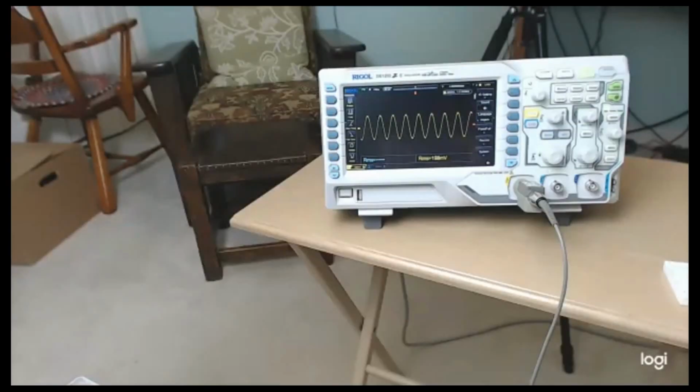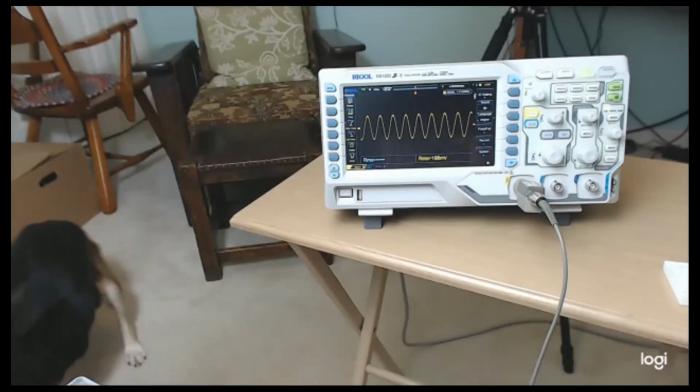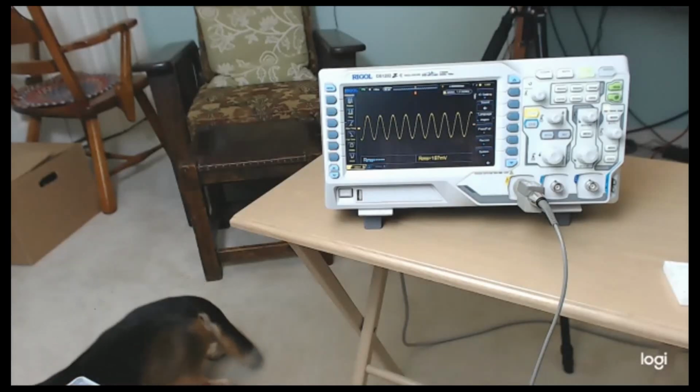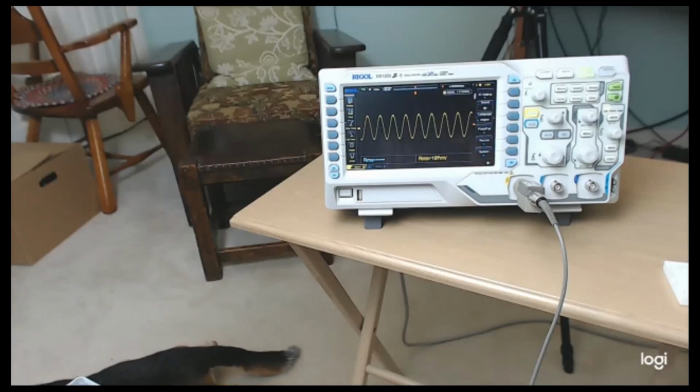It would take 5 seconds. That's how difficult it would be. So once you're in software, those decisions, what you display for the frequency, are trivial. It really is just a couple lines of code to program in the offset. So for my single sideband receiver, I have to keep track of the fact that I have an LO that I'm controlling and a BFO that I'm controlling, and then I have the frequency that I'm displaying, and I have to take care of those calculations in the software.